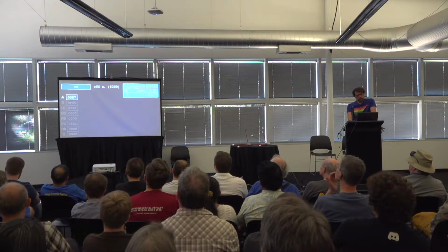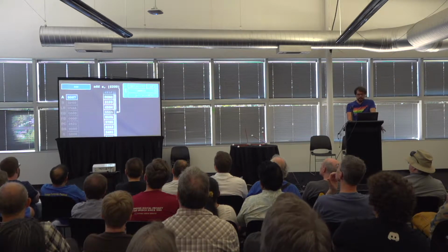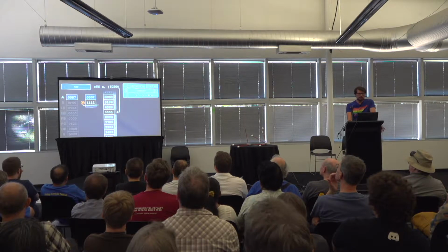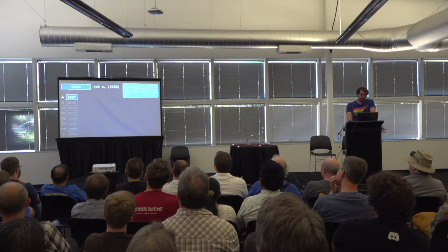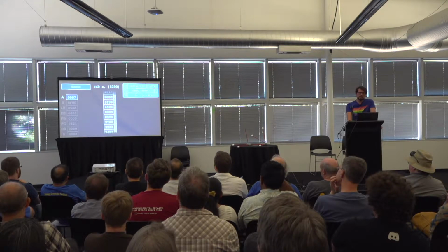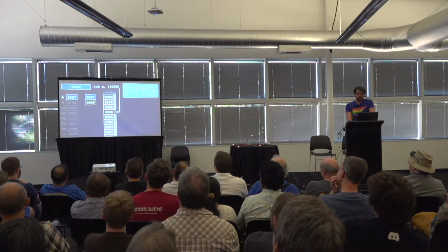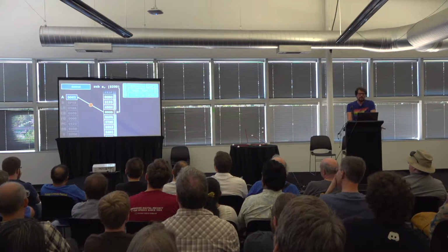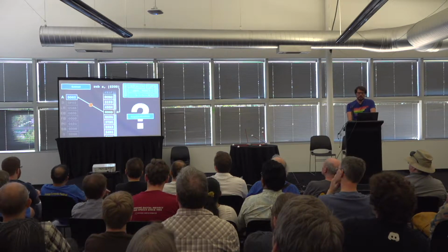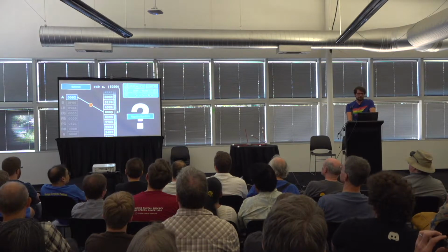The add instruction will look up the contents of a given memory address, add it to the contents of the accumulator, and store the result back into the accumulator. And there's the subtract instruction. It takes the contents of the memory address, subtracts it from the contents of the accumulator, and stores the result back into the accumulator. The result of subtraction can be negative, so we need to talk about how negative numbers are expressed on the AGC.